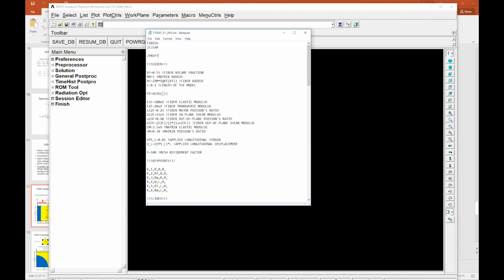It doesn't really matter. I mean, it's a small number, just not to use too much space, because you remember you have a student version, so you're a little bit limited in terms of the number of elements. So it's better to create small models as possible, so that you can later refine the mesh better, instead of creating unnecessary volume, which is not contributing to the accuracy.